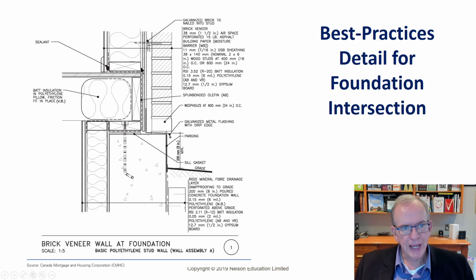And a lot of times it becomes damaged, so it should be fixed with a tuck tape, which is the red tape that you see everywhere, before things are closed up. So very typical. And you can see other things that we've discussed in the course. On the outside of the material, you can have some sort of building paper. If it says asphalt building paper, that's the regular building paper, but you could put a Tyvek paper on the outside. That would be even better.